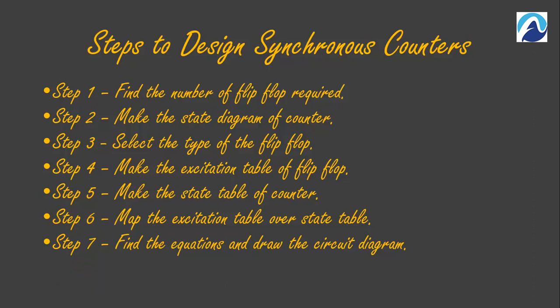The first step is how many flip-flops we require to design a counter. We will see how we can find this number of flip-flops. Step 2 is we need to make a state diagram of the counter. Those who know what a state diagram is, that is well and good. Otherwise, we will see it in the upcoming slides. The third step is we need to select the type of flip-flop we can use.